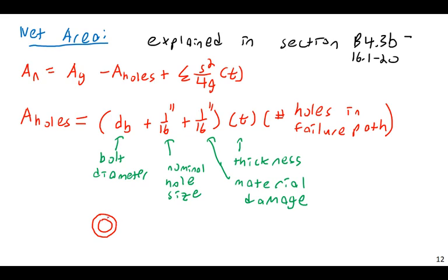But when you drill a hole in a piece of steel, you cause a lot of damage, a lot of minute cracking and fractures. You may not see it with the naked eye, but under a microscope, elsewhere in the material, far away from that hole, you might have nice even grain structures, cooled and heat treated nicely. But everything around that bolt hole is going to be completely mangled at the crystal level.